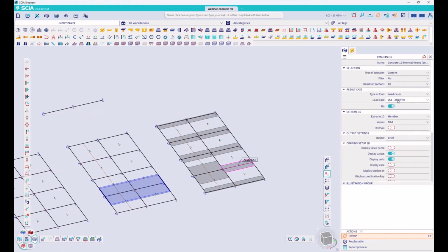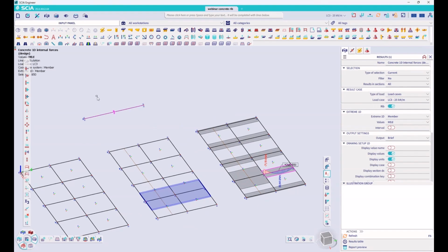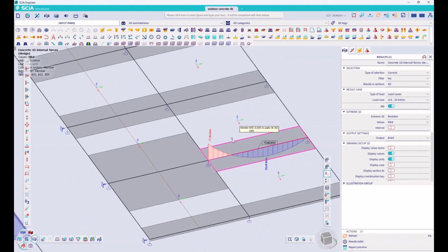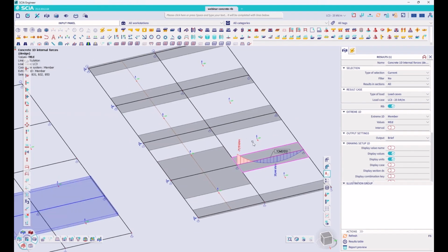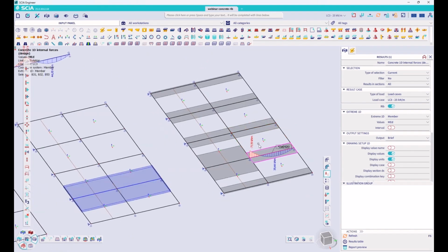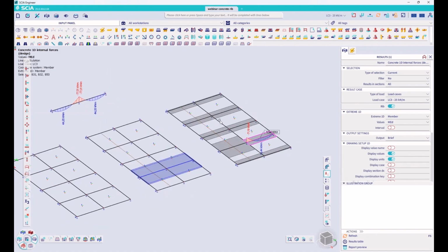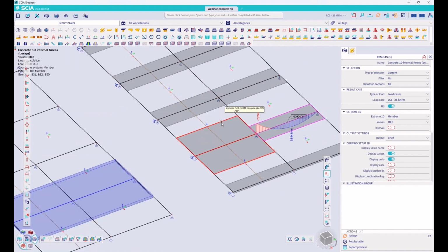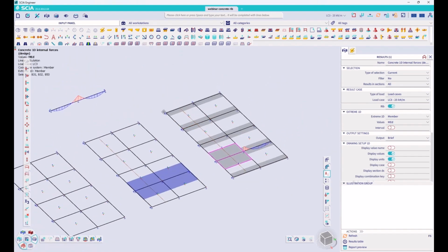You can see by doing so that also the moment force does not equal the moment force that I had from this 1D member. And the reason for that is that in this case, I am taking into account the additional normal force in the plate. So I'm taking into account the normal force that falls outside of this effective width, but I'm not taking into account the moment force in the plate. If I want to take into account also the moment force in the plate, I have to make this rib bigger, give it a bigger width.